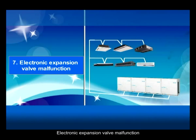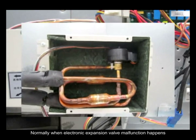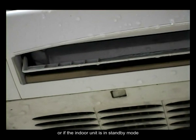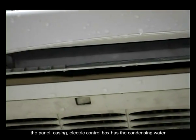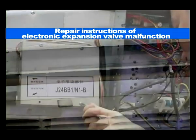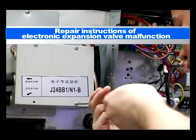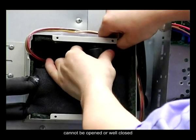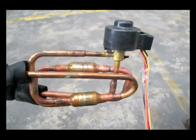Electronic expansion valve malfunction. Normally, when an electronic expansion valve malfunction happens, the cooling or heating performance will be bad, or if the indoor unit is in standby mode, the panel, casing, and electronic control box have condensing water. Repair instructions of electronic expansion valve malfunction. First situation: the electronic expansion valve cannot be opened or well closed, and the valve has no sound of action or the sound is smaller.